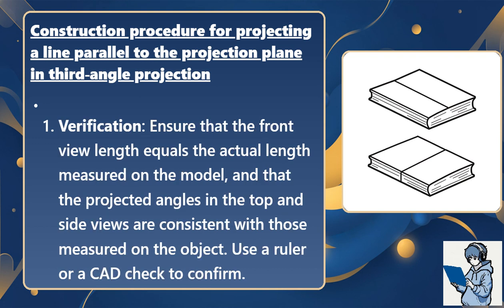Verification. Ensure that the front view length equals the actual length measured on the model and that the projected angles in the top and side views are consistent with those measured on the object. Use a ruler or a CAD check to confirm.